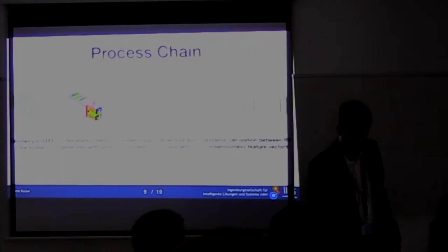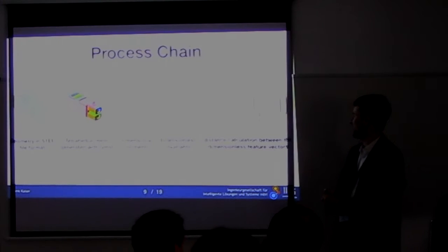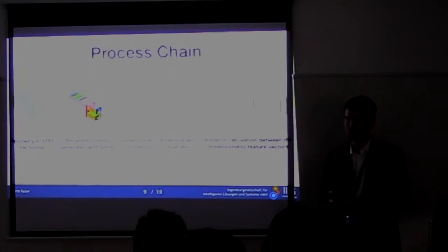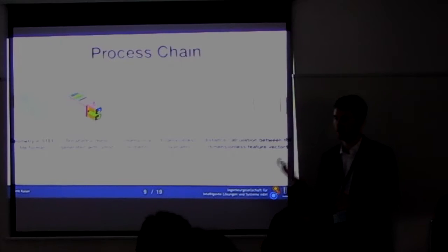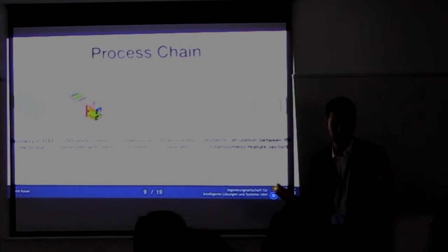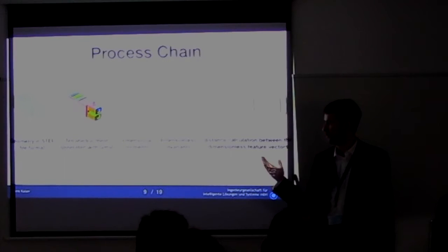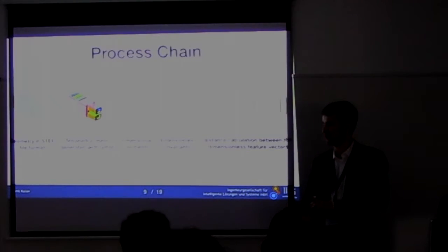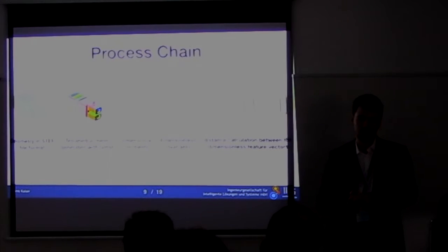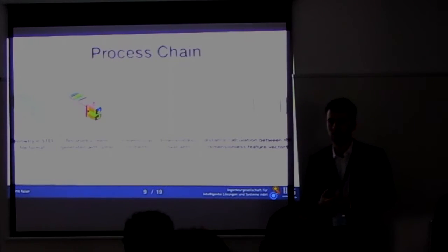And with that, the process chain is completed. We start with a geometry in, for example, step file format, could also be some other format. We just need to mesh it so that we get tetrahedrals, because we need them for the numerical integration.